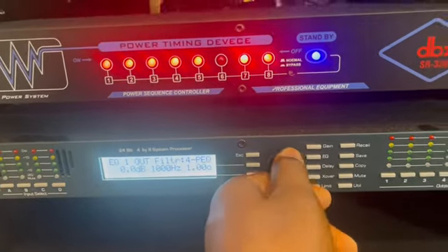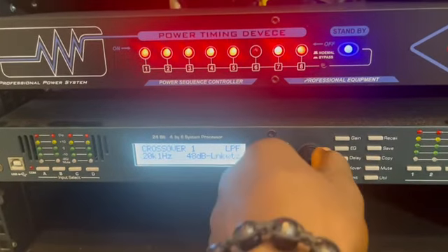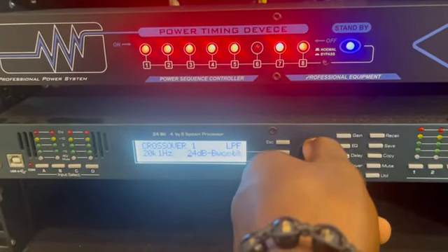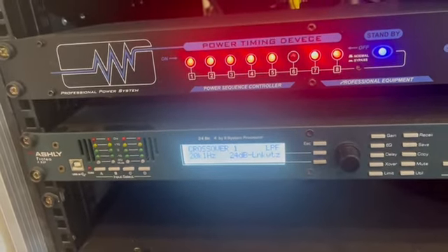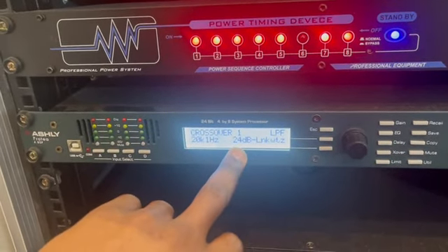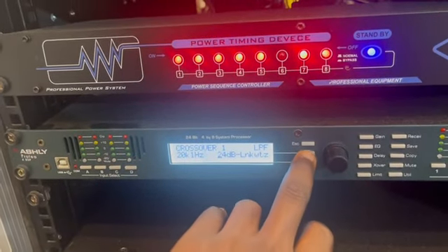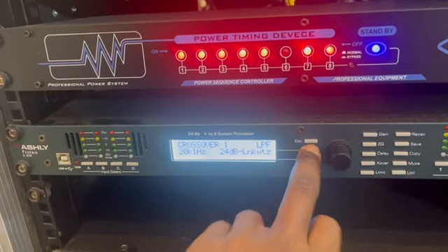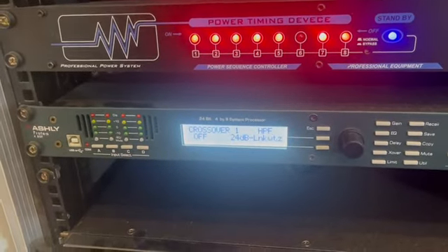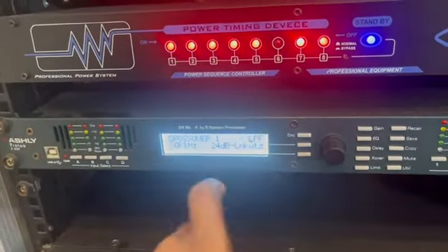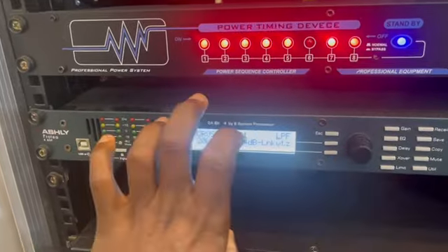Good. So let's say I want to use Butterworth of 24 or Linkwitz-Riley of 24. Right now, I have set the high pass of my line array. Let's say I want to set the high pass: remember the upper toggle button, I click on it and I can change this to high pass. It's on high pass and you see it's off. It doesn't mean what I did here is not working. It is actually working, but I've moved from one page to another.